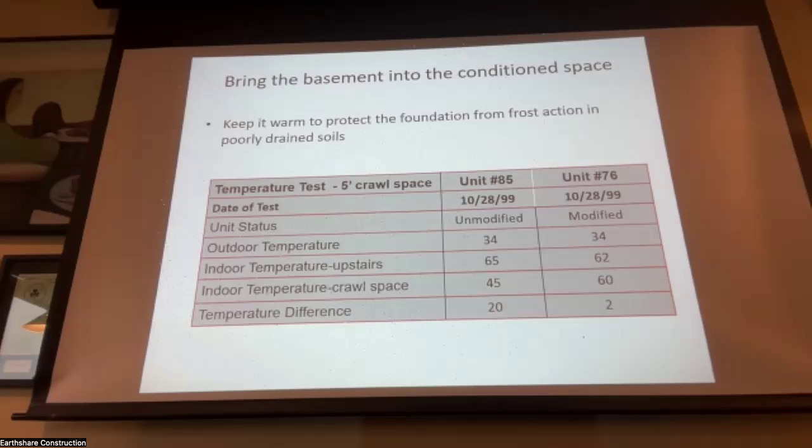If you have a long narrow railroad car, a train, it's got a surface area that's an order of magnitude more in ratio to volume. So ACH doesn't help you, but CFM 50 per square foot of shell works on any shape, and you can compare air leakage from one to the other if you stick to surface area of shell.